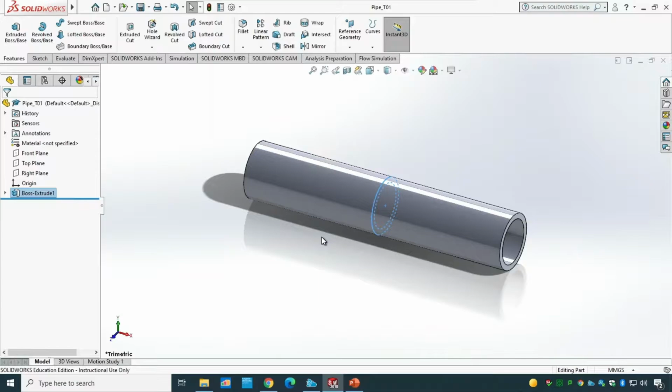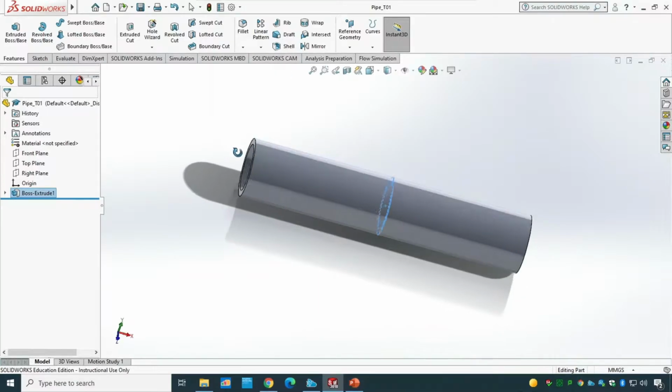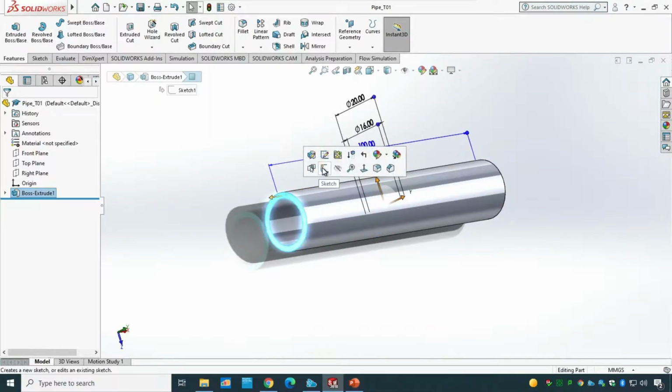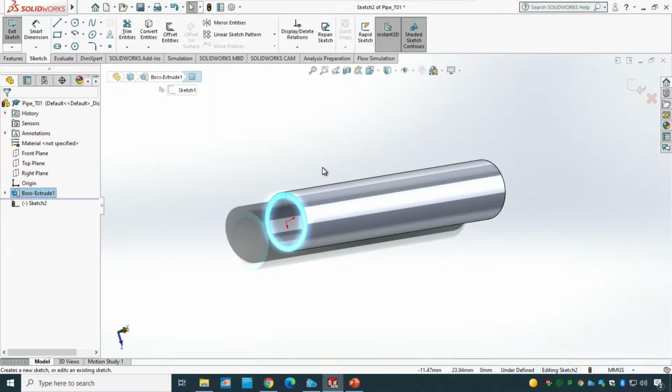But in terms of applying the CFD, I want to define the inlet and outlet. And that's why it's really important to prepare my geometry for it. In order to do that, I need to create the inlet and outlet while I'm here, so once I take it to the flow simulation, I can use those. So what I want to do in here is pick one side, let's say here, click there. And now I want to create a new sketch on that face. And rather than just going and drawing circles on that, you already know how I would be able to do it.